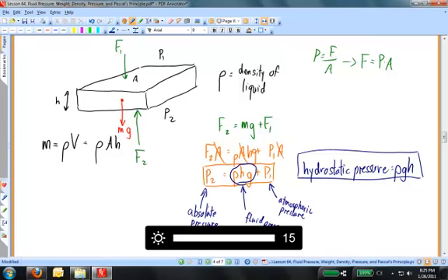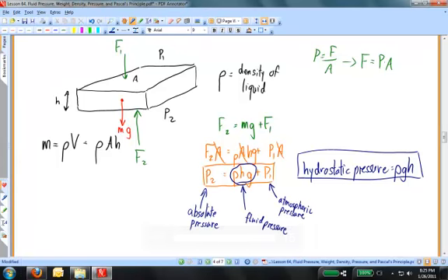So this fluid pressure is due to gravity. If there's no gravity, there's no hydrostatic pressure. We're going to be working mostly with liquids, and most liquids are practically incompressible. It's possible to compress a gas, but it's really difficult to compress a liquid. And so from this point onward, we'll say that our ideal fluid has a density that's everywhere the same.